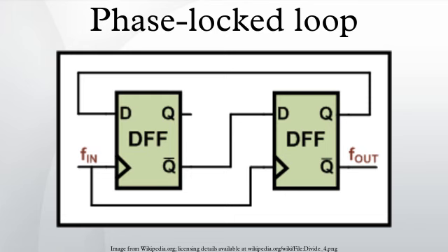PLLs are ubiquitous. They tune clocks in systems several feet across, as well as clocks in small portions of individual chips. Sometimes the reference clock may not actually be a pure clock at all, but rather a data stream with enough transitions that the PLL is able to recover a regular clock from that stream. Sometimes the reference clock is the same frequency as the clock driven through the clock distribution, other times the distributed clock may be some rational multiple of the reference.